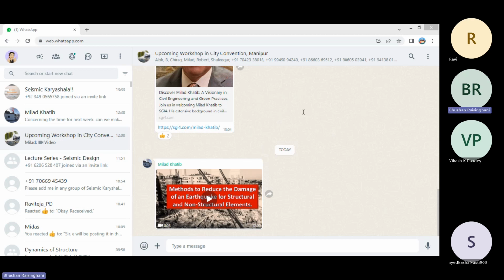that has not more than, okay, this is the minimum requirement, 100 mm, but it may be relaxed to 150 mm if the maximum distance between cross ties or parallel legs of links or ties is limited to 200 mm. So you cannot go below 100 mm, and you cannot go more than 1/3 of the minimum member dimension and 6 times the longitudinal bar.